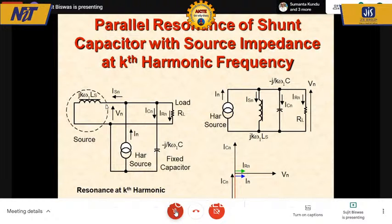At the kth harmonic equivalent circuit, this capacitor is having a reactance of 1 by k times. And if you once again readjust this into the right hand side figure, where I intentionally put the source reactance at the kth harmonic and the effective capacitance of whatever is there on the bus at the kth harmonic, there is a chance that these two can resonate. There is a chance, we don't know. It can resonate at the kth harmonic.